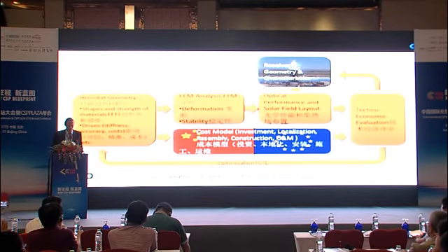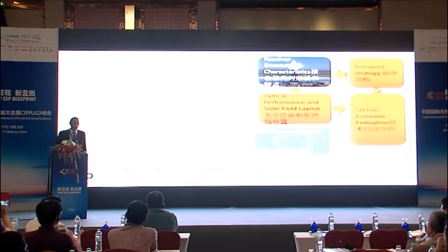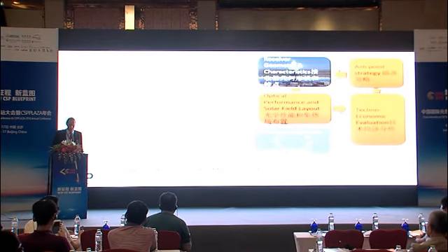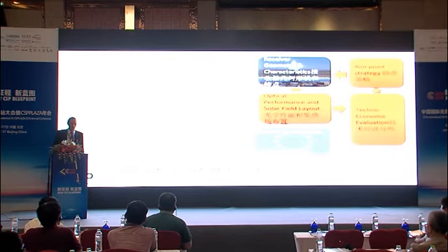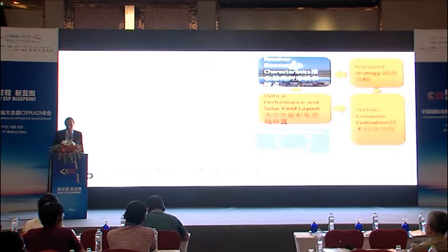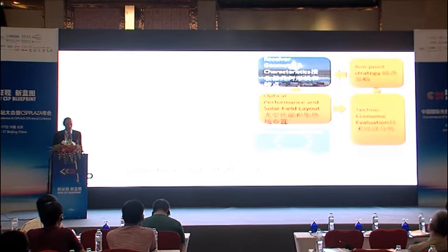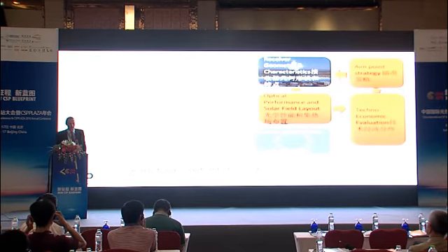This is technology development, but I'm just talking about solar field strategies today. If we assume in the current optimization that we have a very good technology already at hand, and we now optimize the solar field layout, for example for a central receiver plant, the optimization goes around the receiver geometry, the receiver specifications on flux levels, for example, and the optical performance of the solar field. Then again the cost strategy is paired with an aim point strategy, and you run that and constantly change the geometry of the layout and find out if it's getting better or worse.